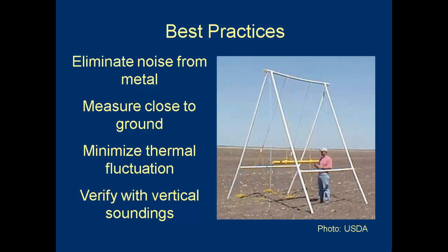Zero-level drift in sensors arises primarily from imperfect compensation for thermal distortion of the sensor housing and thermal characteristics of array components. For applications that require the greatest absolute accuracy, the sensor should be allowed to stabilize with power on at ambient temperature and shaded from direct or fluctuating sunlight.